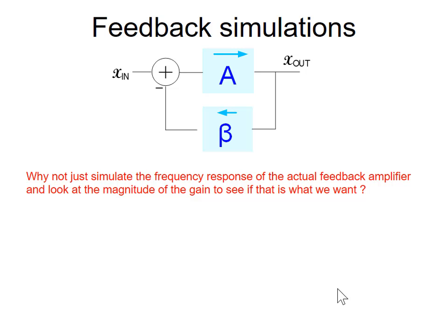And furthermore, probably all you're going to be doing at this point is changing that compensation capacitor. So you just go in and say, I'm going to change the compensation capacitor now and try to bring that magnitude response into what I want it to be. A lot of times you do that with the phase margin. If the phase margin is not right, too high or too low, increase or decrease the compensation capacitor a little bit to bring it in.